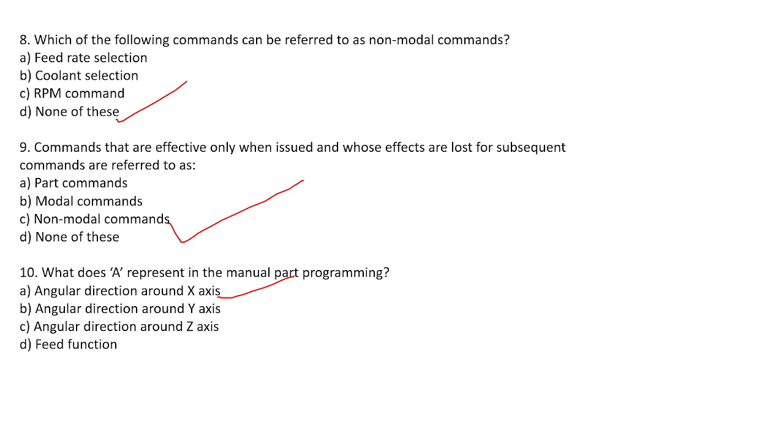But those terms are not denoted by G17, right? They are typically denoted by G01, G02, G03. So for that question the answer will be none of them, because that G code gives the command to control the machine tool's movement, but inside that, for every operation there is a specific code. For line interpolation there is G01, circular interpolation G02, and for dwell, if I'm not wrong, G04.